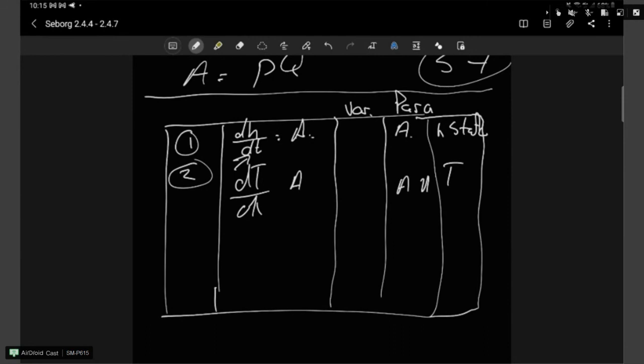CP will get you just now. So that assumption is a valid assumption. The reason for that is the flow rate of the steam is usually much, much higher because it's gas vapor phase, obviously. Reynolds number is much higher, so you have a lot more heat transfer. So the limiting step is between your stagnant or slower moving process liquid or fluid and the area associated with that, so that convection term. So that's a reasonable assumption to make.